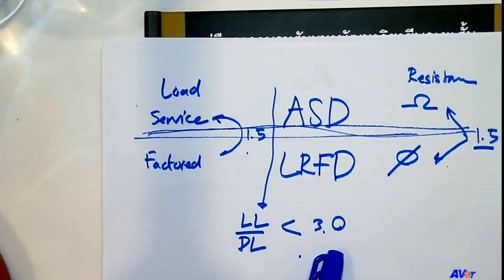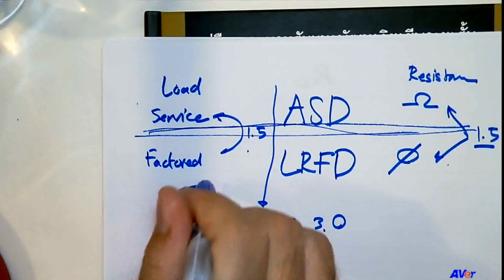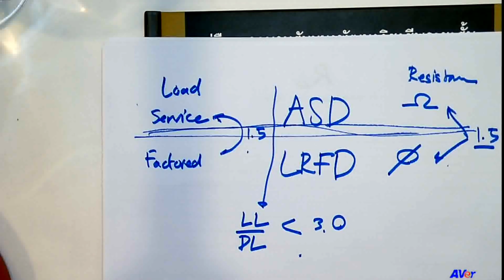And if you ask me, it makes sense because the LRFD puts a lot of emphasis on the uncertainty of the load. So if you have a very, very large live load, how can you be sure about it? You would rather provide the structure on the safe side, right, than become sorry later. Better be safe than sorry, they say. Okay? So that makes sense to me.